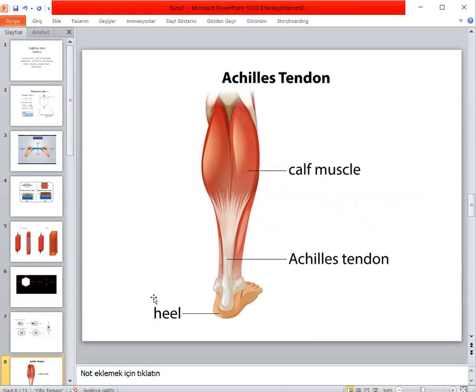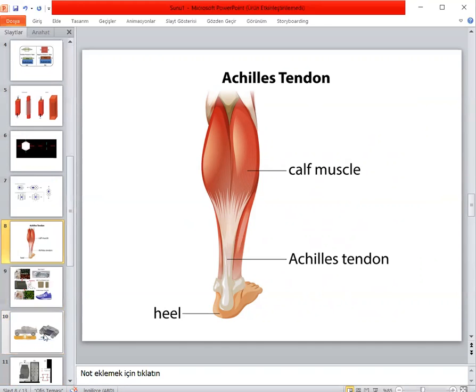In nature, we can see negative Poisson's ratio, I mean auxetic materials, in our muscles. There is a link between muscles and the bones. This means the Achilles tendon. The Achilles tendon has a negative Poisson's ratio. It's an important point that, for example, if there's a tensile force, our cross-section is increasing, and the stress transfer to bones is decreasing because of the increased cross-sectional area.